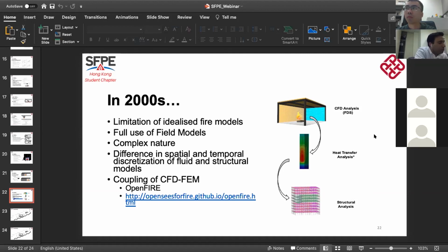If you are using engineering fire models, maybe you are missing some assumptions. So maybe that's why they're giving lower temperature, maybe not pure energy conservation. As I said, the parametric curves suggested by Patterson are also based mostly on tests with wood cribs. So for different material, it might not be the same.